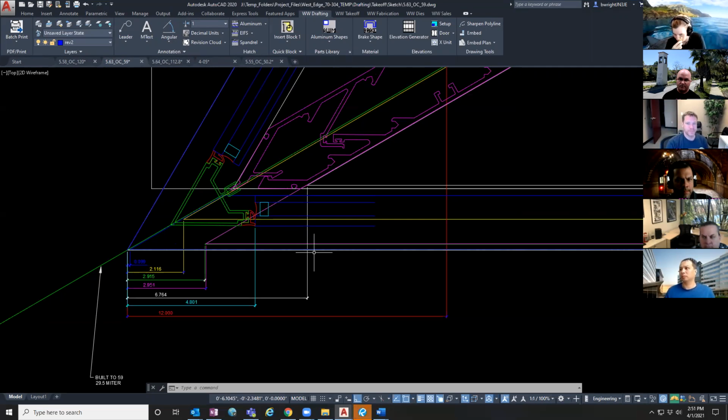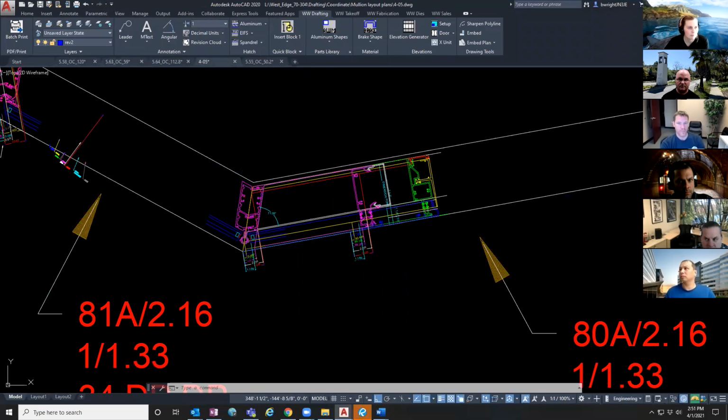Yeah, but the bite of the glass should be sized based on the floor plan dimension point to dimension point, not based on the verticals. Correct. So it is okay to order the glass before you size the unit, because you size the frame based on the unit per rotation, but the glass is everything per floor plan, dimension point to dimension point.